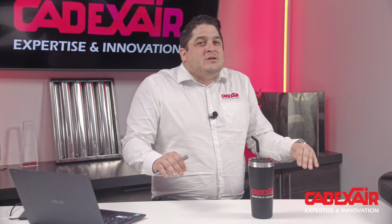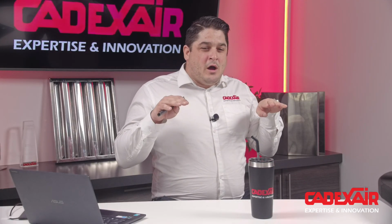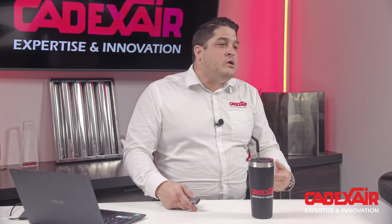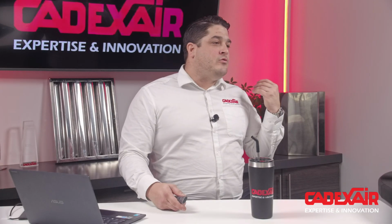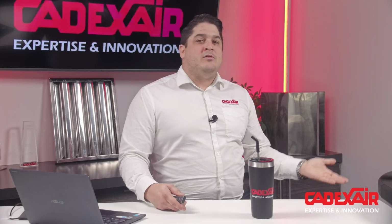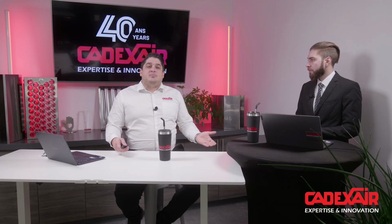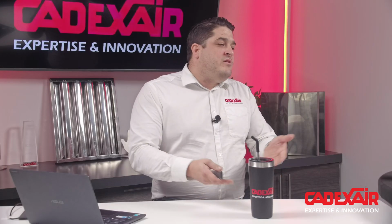So you have to lower. At the end of the day, you need to get a temperature on the top of your equipment, and the BTU is how fast you will reach this, because almost all equipment will try to get to a set point, so they will just get there faster or slower. So we will work as per what temperature will be final on the equipment.